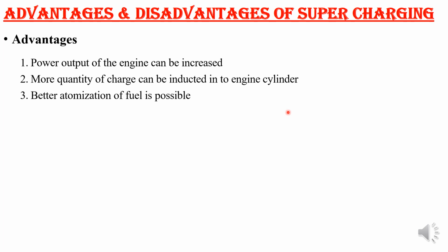So better atomization can be obtained by the supercharging of the engine. Next, better mixing of air and fuel can be obtained. In an SI engine, we are mixing the fuel outside the engine. Hence, while supercharging, what will happen? Density is more, hence the fuel can combine with the air in a better way compared to that of